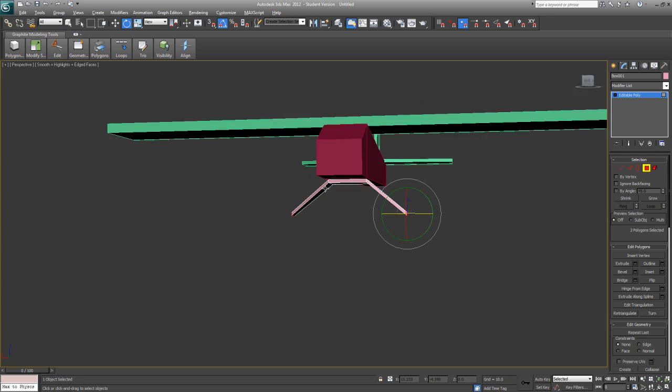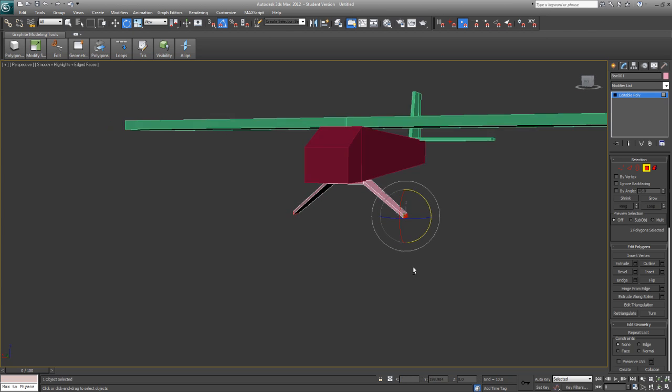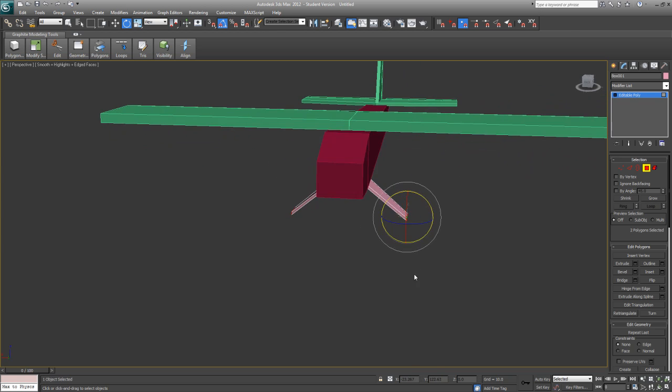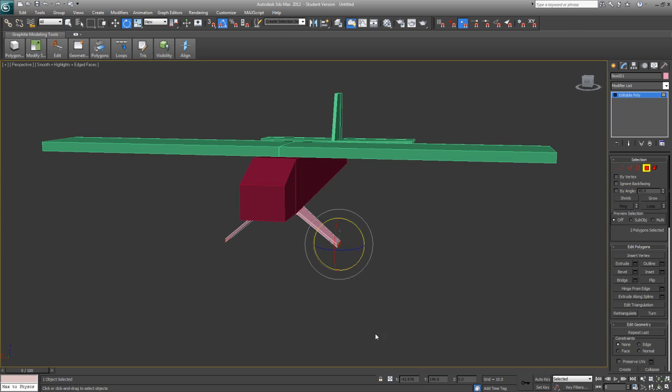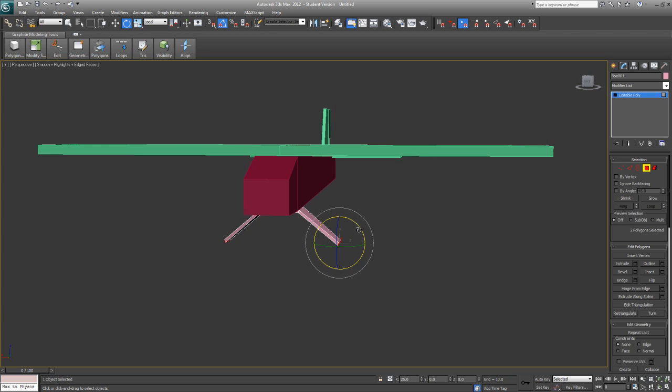So if I hit the Rotate tool, I've got them both selected. You'll see if I rotate them, I get really weird results going on. That's because they're being rotated based on the view, and that's controlled by this little box here next to it. If I go all the way down here to local, it's going to pivot both of these faces on their own little centers. So I'm going to pivot these, and you'll see now they're rotating correctly. So I'm going to rotate them out like that.